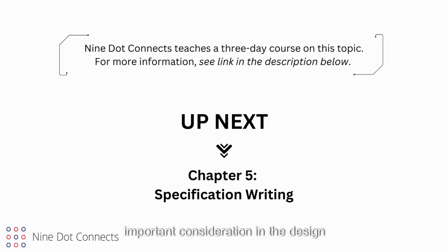DFX is an important consideration in the design process. Failure to recognize it can lead to respins and other delays to fix it. Test is not a single operation in PCB assembly. Normally, it takes more than one test technique to ensure the PCB is manufactured correctly with no defects, and the PCB is functional from the design and engineering standpoint.